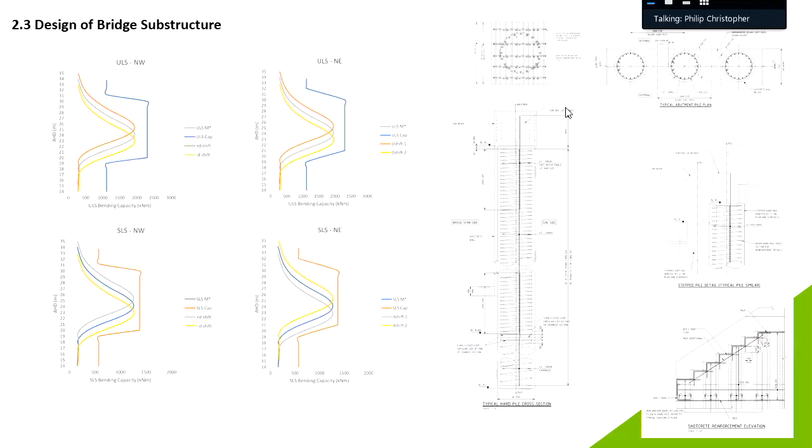Then in addition to that, the challenge of secant pile in this job was the starter bars coming up and the detailing as per 5100. There was a bit of a clashing, so we were invited to site and trying to tell them which ligatures, shear reinforcement, can be actually sized a bit further apart to make room. So that's a bit of an interesting design and construction alteration on site.